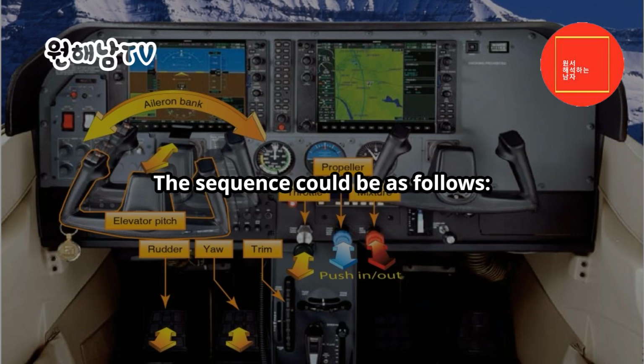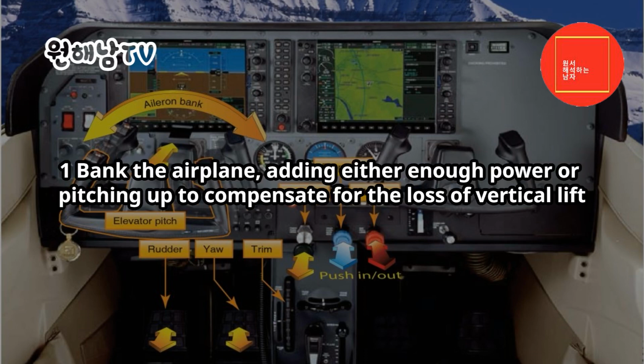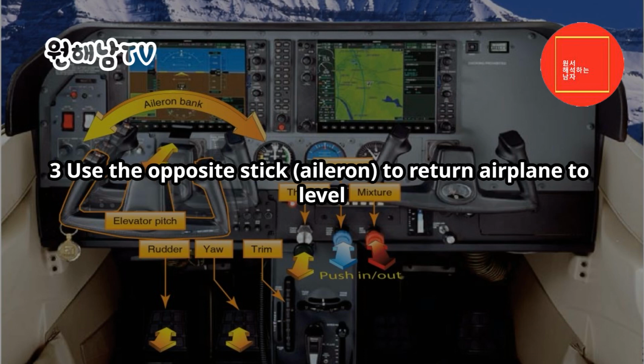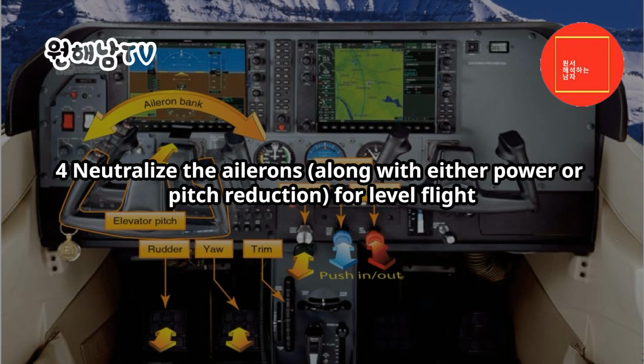The sequence could be as follows. 1. Bank the airplane, adding either enough power or pitching up to compensate for the loss of vertical lift. 2. Neutralize controls as necessary to stop bank from increasing and hold desired bank angle. 3. Use the opposite stick, aileron, to return the airplane to level. 4. Neutralize the ailerons, along with either power or pitch reduction, for level flight.